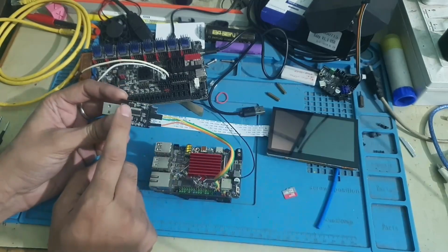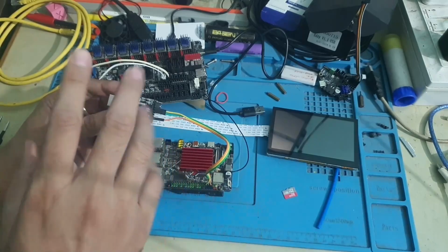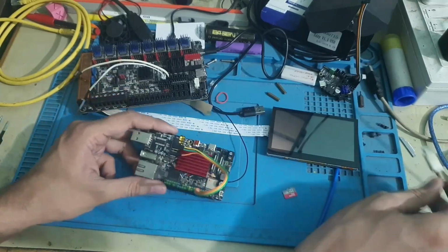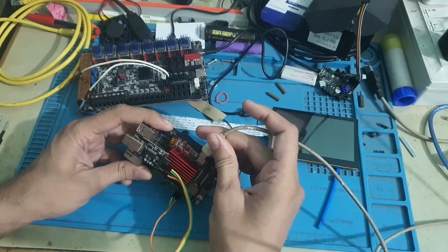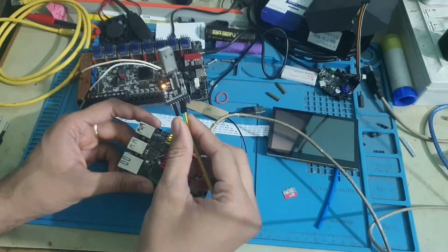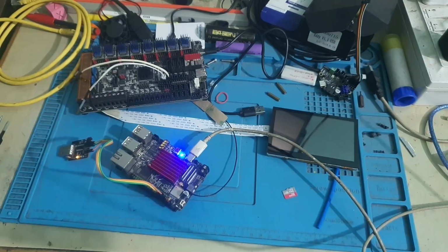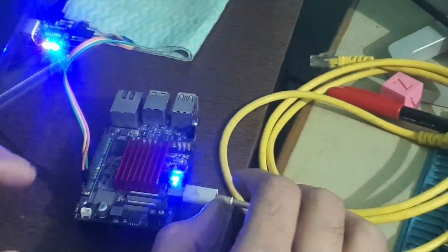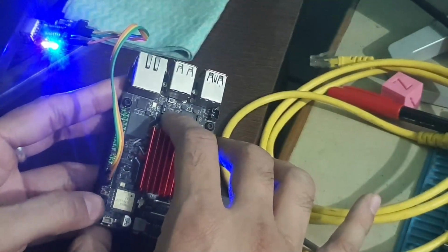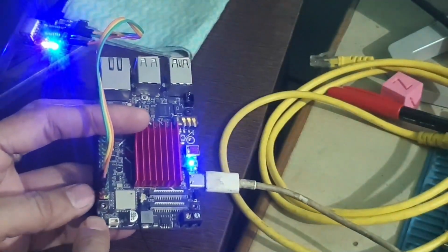Now you need to plug this into the computer and go to the terminal, and it shows you the communication COM port. Attach the power by USB, so attach this to the computer, and then it shows you a port. Before you attach any power, you should take care of the switches, so your USB OTG is off and your eMMC is off.